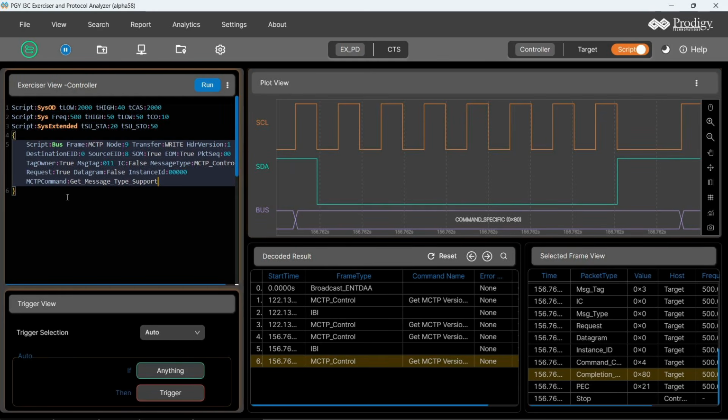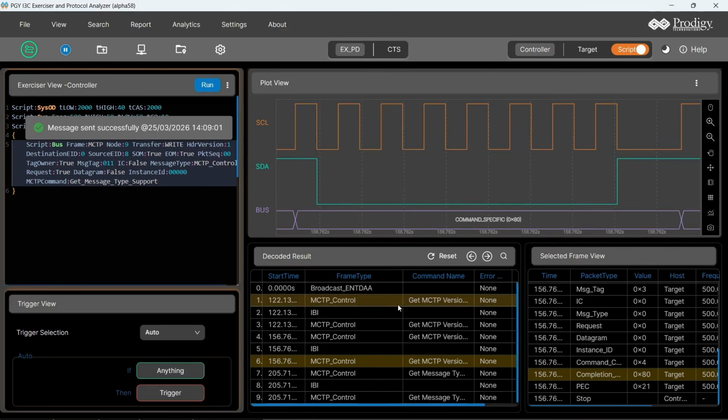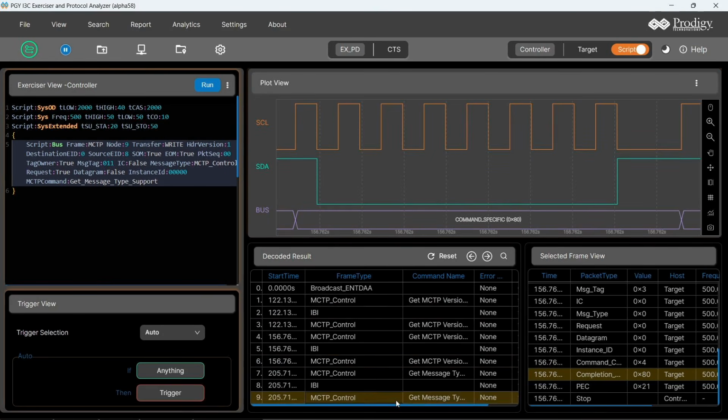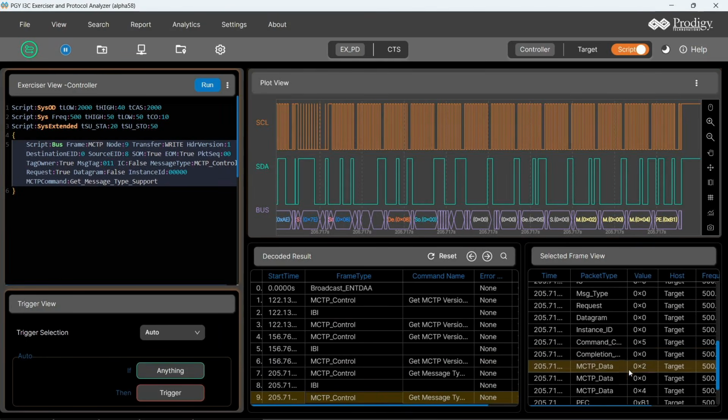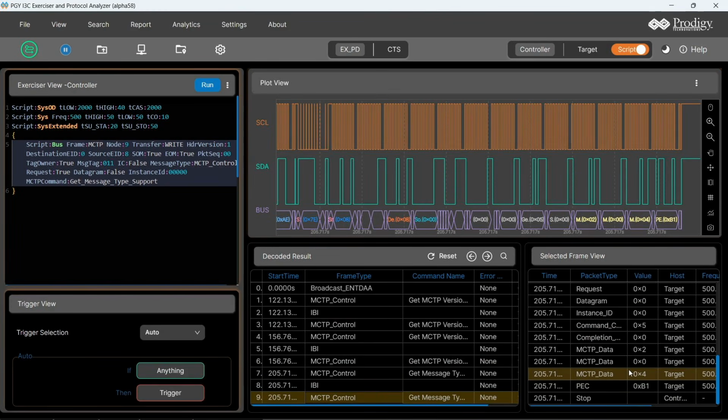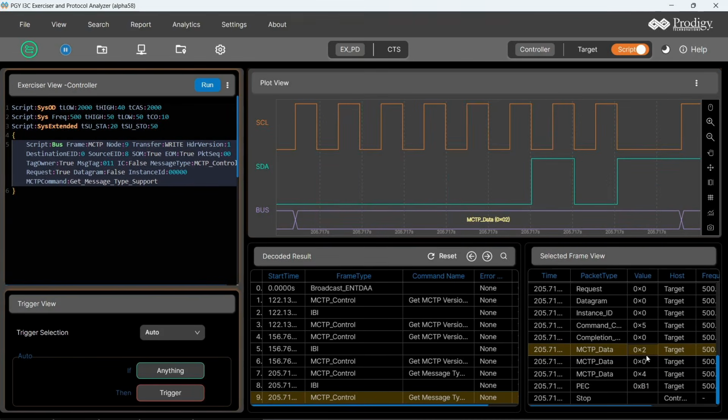This command enables the management controller to determine the MCTP control protocol capabilities supported by the connected endpoints and retrieve the list of available message type. In the response, the endpoint returns the list of message type numbers with each number represented by 1 byte. That is it supports two message type, that is 0 stands for MCTP control and 4 stands for NVMe-MI.